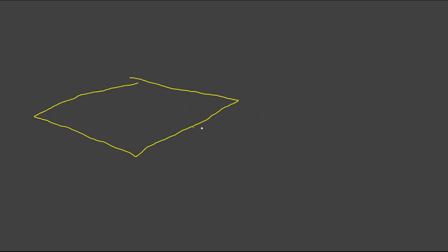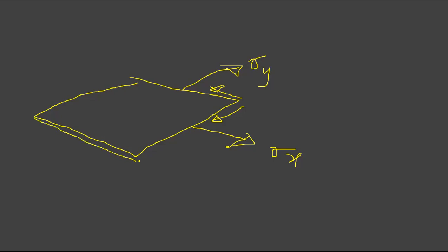So in your Mohr circle, you remember sigma x. This is the shear stress, right? Shear stresses. Sigma x, sigma y. What the plane stress assumption is, right? So sigma z is what? 0. So you only reduce it to a plane, right? So we'll do an example.